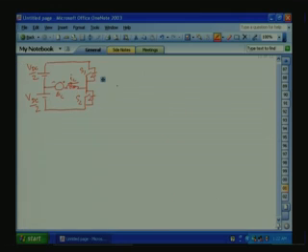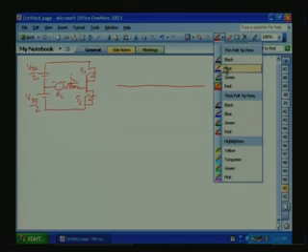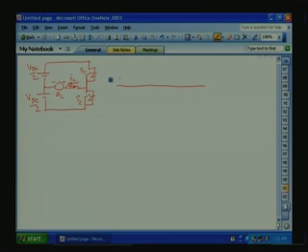So current has to be controlled depending on the load. So this is the current we want, and we will introduce the hysteresis band, so that the current ripple is controlled within this band. So let us enlarge for analysis. Let us say this is the band. So this is the IP, this is the IV, upper band and lower band.